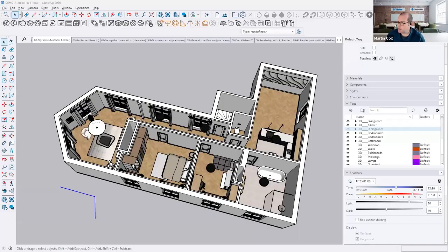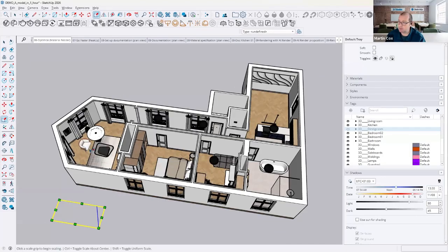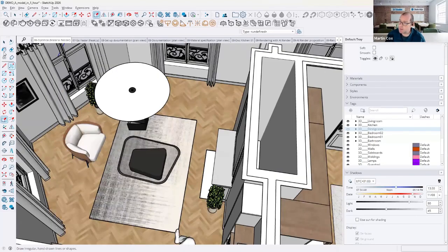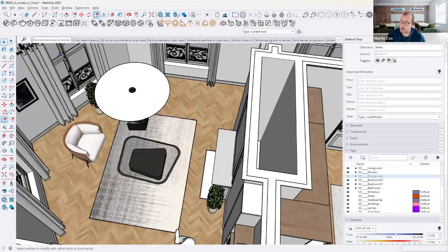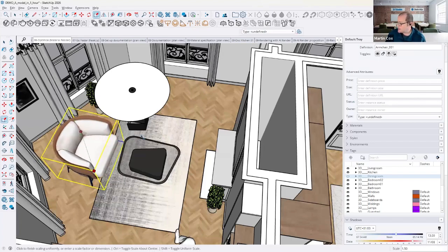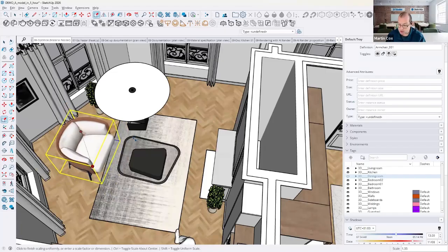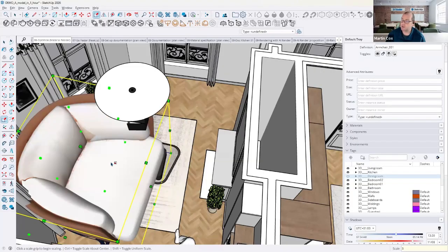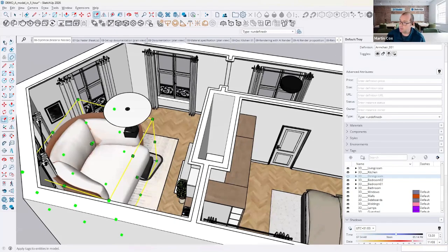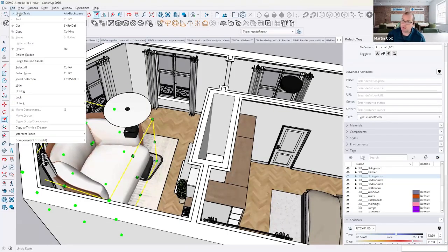How to change the dimensions of those dynamic objects? Scale. Using the scale tool there will scale any particular object. Depending on what size the chair is, if I choose scale and choose the corner, which means it's a uniform scale, then down the bottom right-hand side you can see what scale I want to add. If I say I want a scale of 3, that will make it 3 times the size. Every gaming room dream, that chair. But yeah, let's undo that scale.